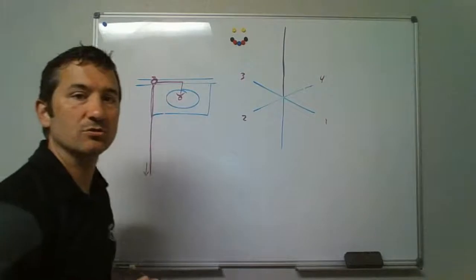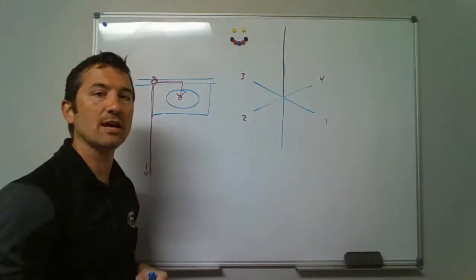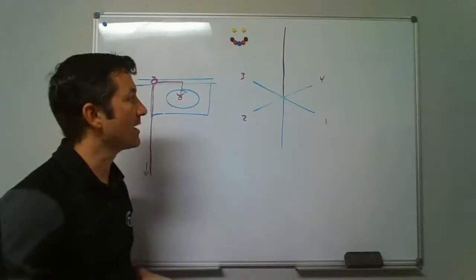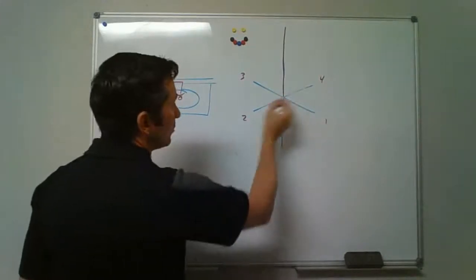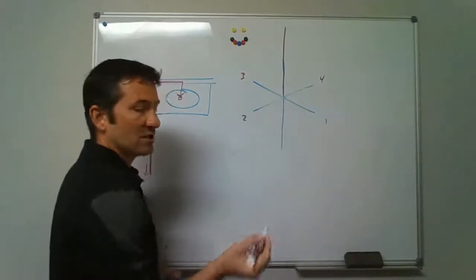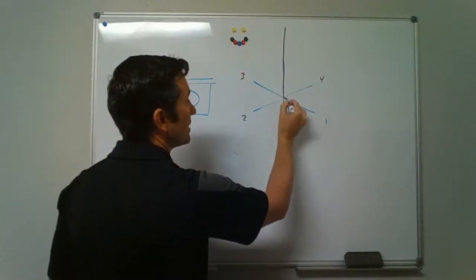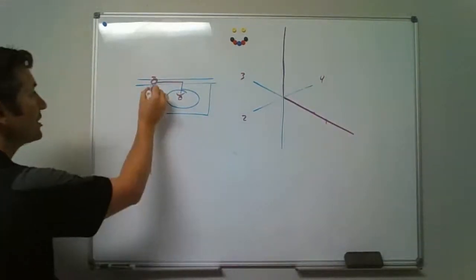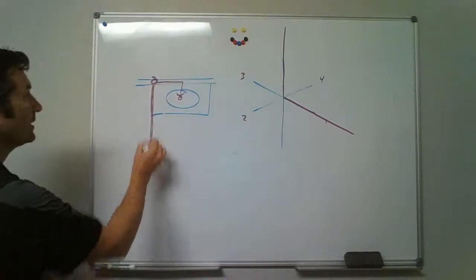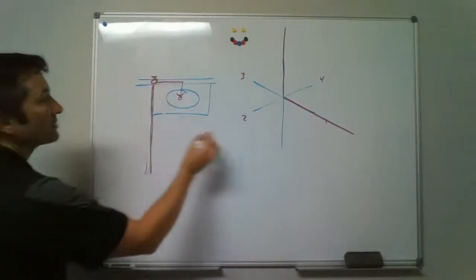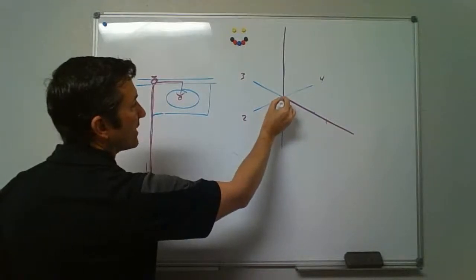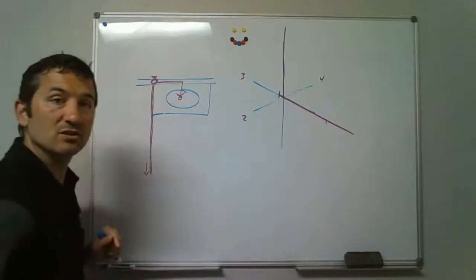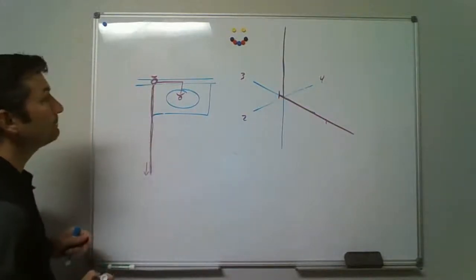As we draw that horizontal drain line, since it's the first horizontal line you're drawing, you get to pick which angle you're going to draw that at. Do you want to come down towards the number 1, 2, 3, or 4? So let's just go ahead and do towards the number 1. You trace that line out going that way. You just drew this horizontal line. We show the symbol for the clean out in the back, so don't forget to extend that straight out of the back of that line, and then the clean out line goes straight up and down. There's this for the clean out.